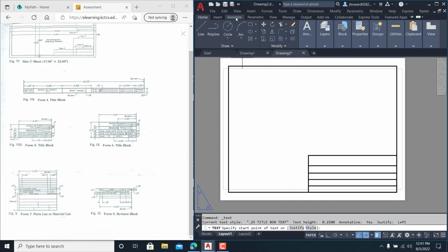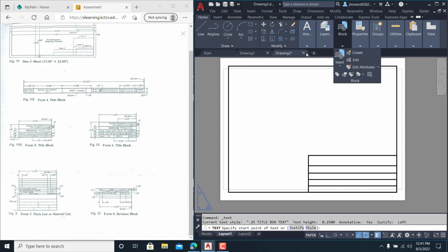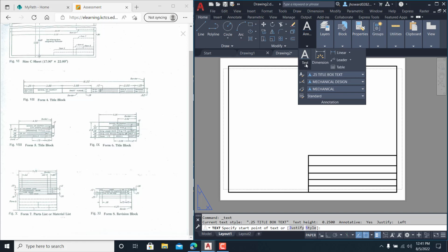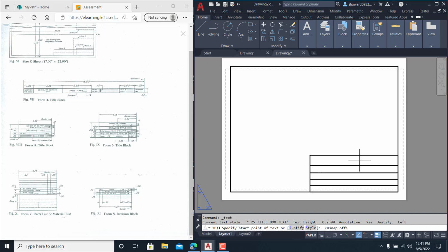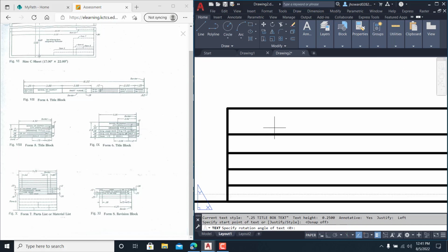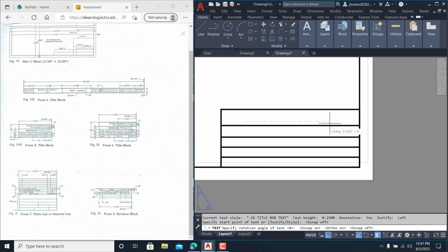And I just got to make sure my layers on that. I didn't make a layer for that. I was going to use the 0, but you'll have layers set up for it. I go in here and again, let's use the single line text, that's fine. Turn off my object snap down there so it doesn't snap to everything. And I put ortho on, just keep it straight there. But for this college, Big Sandy CTC, and what I'm using there, I'll click.